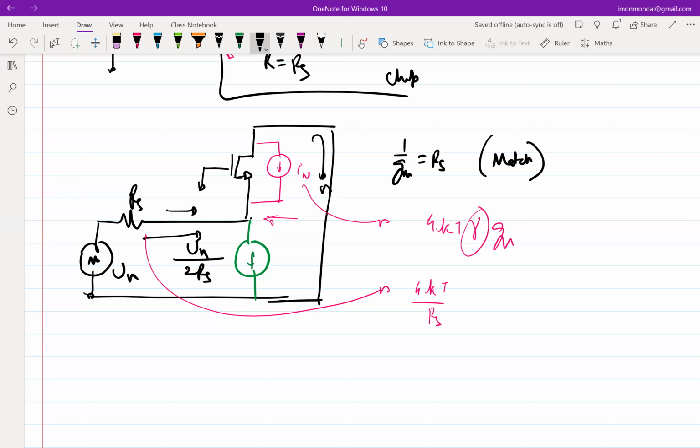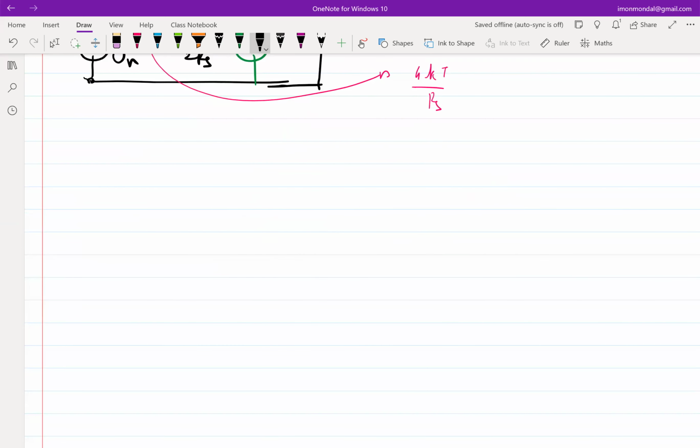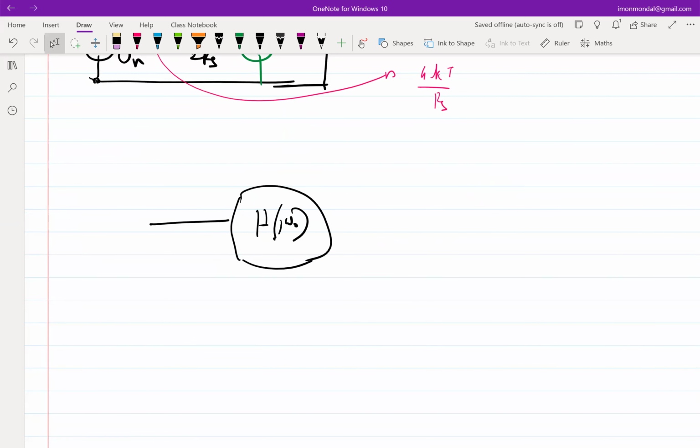Now, to appreciate what is the alternative solution, I would take a detour and show you one topology which is generic, nothing to do with the transistor per se, right? So let's say you have some block which has a transfer function H(jω). So at ω0, you are going to have some mod of H and some angle, right? Typically, it's a phase lag, right? You can also have phase lead at certain frequencies, but let's assume phase lag. So you're going to have mod of H e^(-jφ).